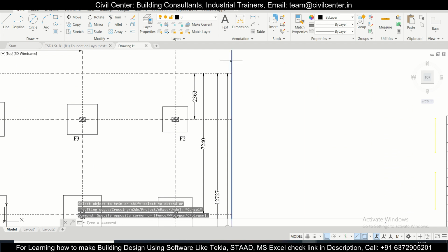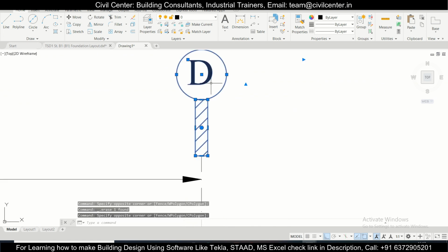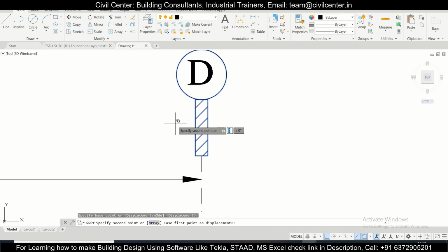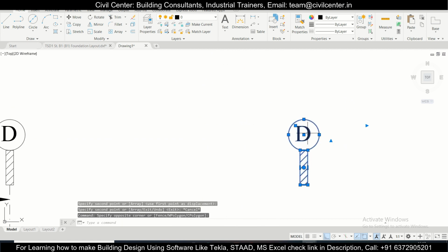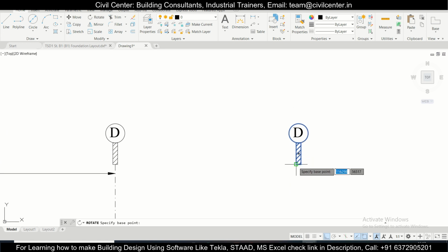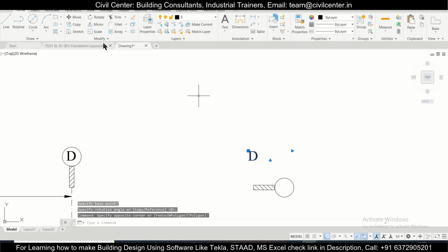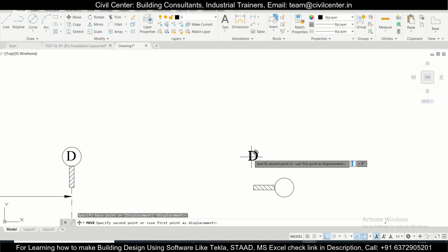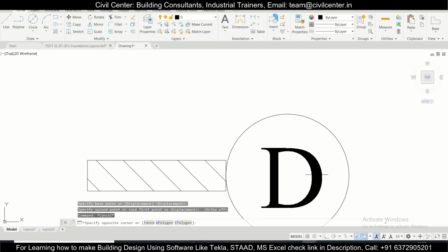After this is trimmed, you can delete that, and after that we'll select the entire one first and then copy that to here, and after that we'll select this and deselect this using the shift option with the option of rotate, and rotate that like this, and then select this, move it to turn on the ortho, turn off the ortho actually, and we'll name it as,